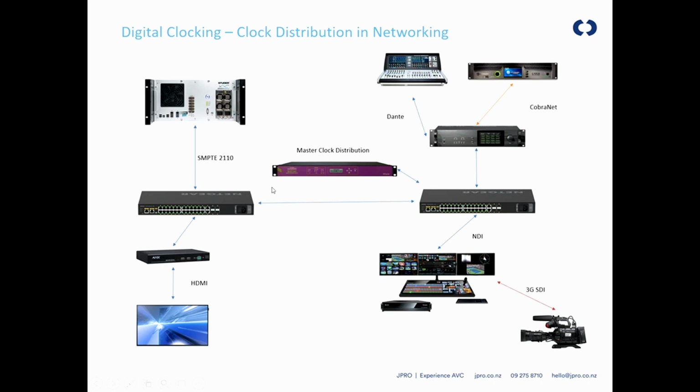I wanted to illustrate it this way again, because once again, you have a video encoder, a video over IP product that is supplying clock to an HDMI device, and it's working through that mechanism. Of course, we're talking about a very audio thing, but it affects video because video also uses time sync clocking to play out frames on time. So your audio and your video frames play out in sync. That's the clocking that's happening there. But more importantly, we need to understand that as much as this is audio, it does affect the video side equally so. So this is what a network distribution system would look like.